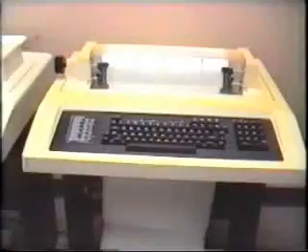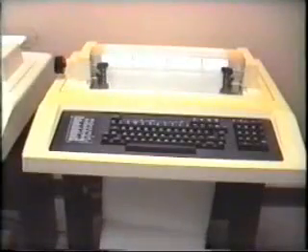The SER is constantly monitoring the status of each input point and prints out a detailed record whenever the status changes. A typical SER printout gives the exact time of the event down to the millisecond. It can distinguish between two events occurring 1 millisecond apart.